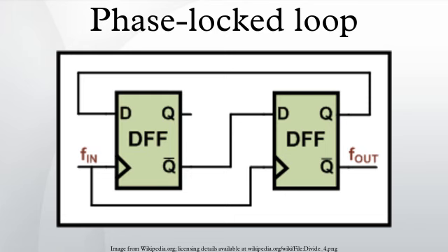or CMOS. Another desirable property of all PLLs is that the phase and frequency of the generated clock be unaffected by rapid changes in the voltages of the power and ground supply lines, as well as the voltage of the substrate on which the PLL circuits are fabricated. This is called substrate and supply noise rejection. The higher the noise rejection, the better. To further improve the phase noise of the output, an injection-locked oscillator can be employed following the VCO in the